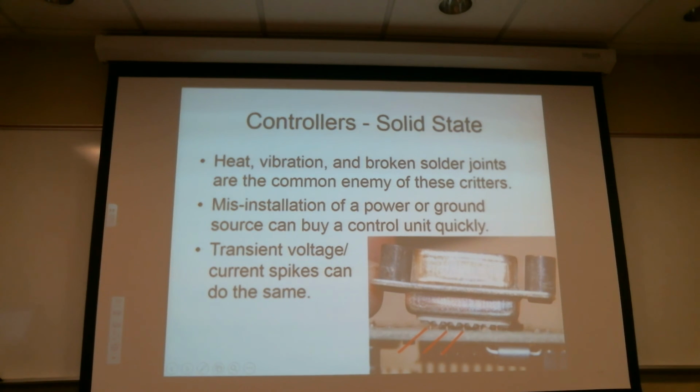Now, what was interesting about this was with all those pins that were broken, the only symptom that was happening was every once in a while, the fuel totalizer, the amount of fuel it was saying it was getting, seemed to slow down a little bit. Well, what was happening was that lead was disconnecting, so the pulses from the transducer weren't all being counted. So it was using more gas than it was thinking it was using. So there you are flying along, fat, dumb, and happy, and it's saying, yeah, you got plenty of gas. Only you don't. That seemed like a dangerous situation to me.